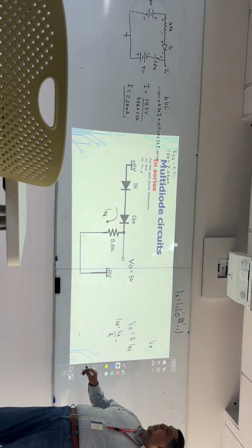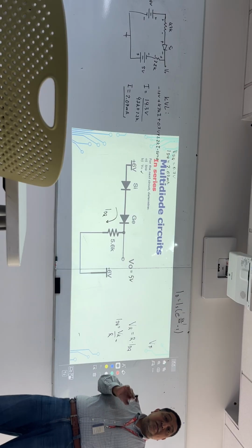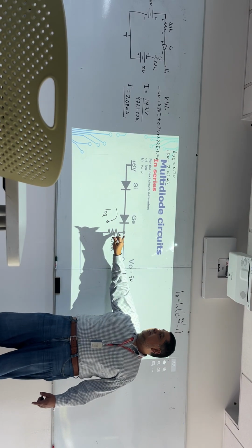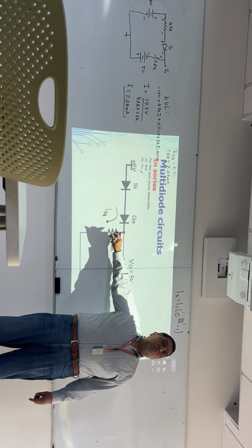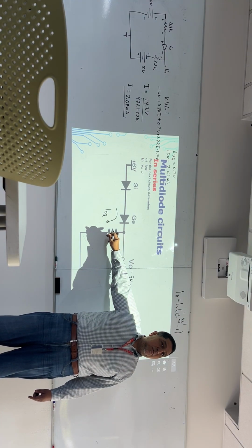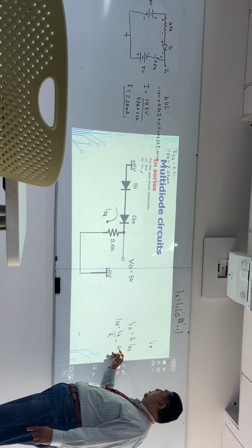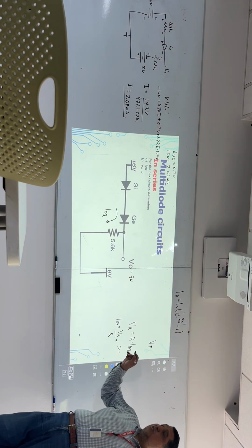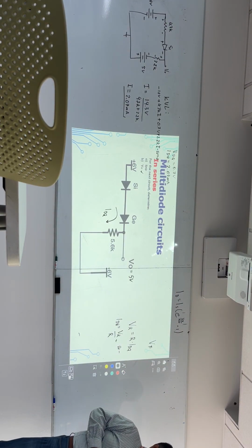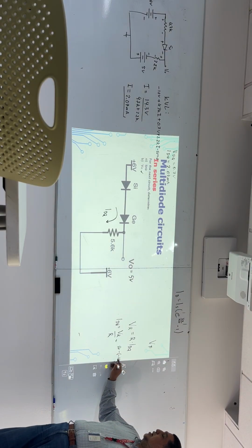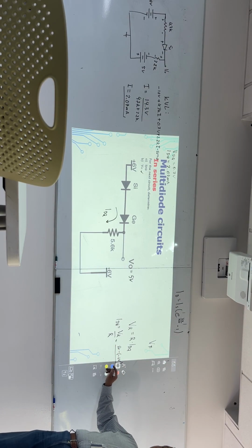Subtracting. Well, using sort of like KVL. Subtracting, again, towards the direction of the current. First, this side of the resistor, what voltage do I have here? V0, or 5 volts. Yes, sir. Minus, the other side of the resistor, what voltage is that? -6. -6, but please be extremely careful because I have this minus, minus.